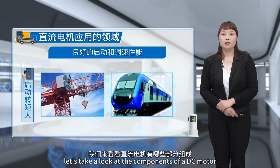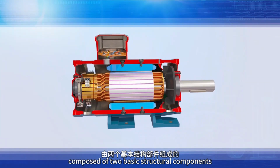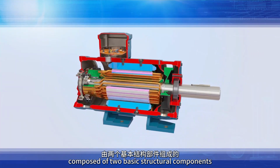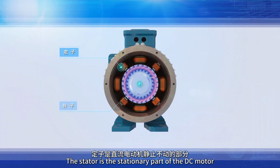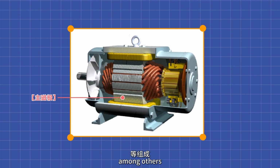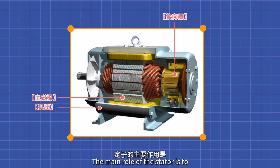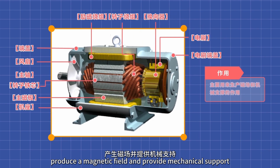Next, let's take a look at the components of a DC motor. A DC motor is mainly composed of two basic structural components, the stator and the rotor. The stator. The stator is the stationary part of the DC motor and consists of the main magnetic pole, commutating pole, motor base, and brushes, among others. The main role of the stator is to produce a magnetic field and provide mechanical support.